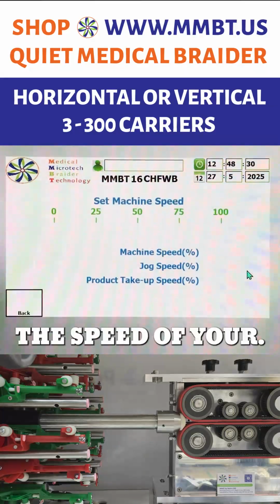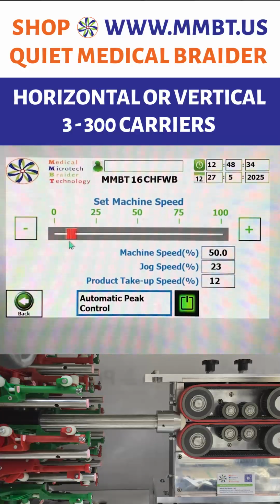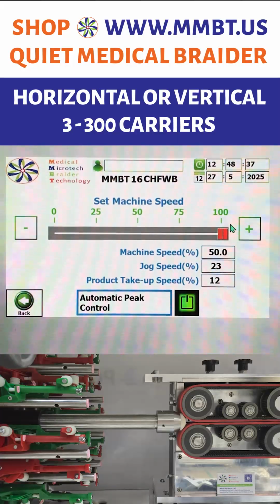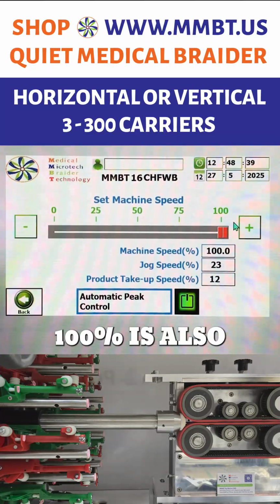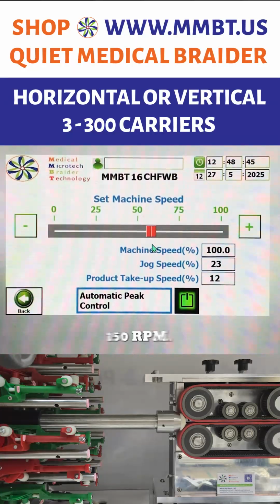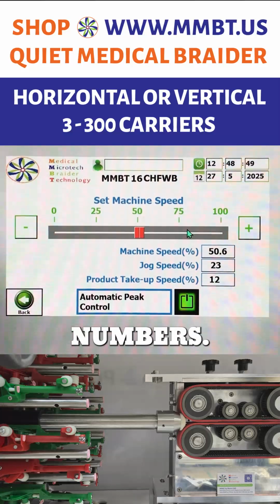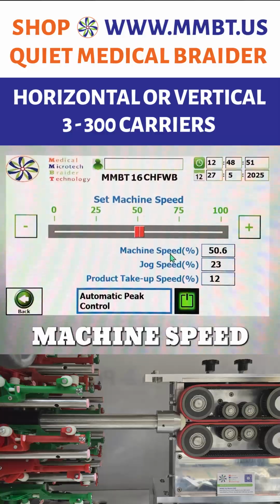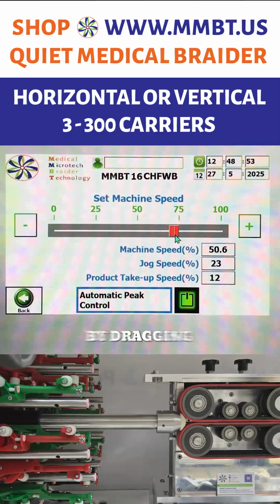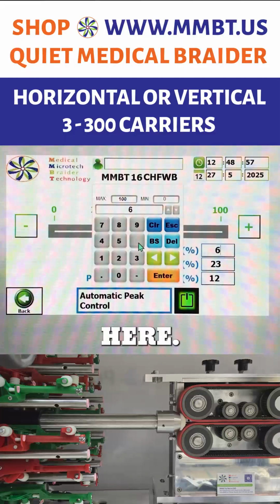You can adjust the Braider speed anywhere from 0 to 100%. 100% is also 300 RPM. So at 50, that'd be 150 RPM, to those of you who use those numbers. You can adjust the machine speed either by dragging this or putting a number here.